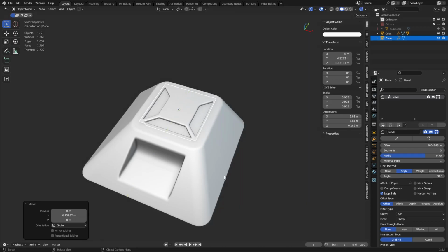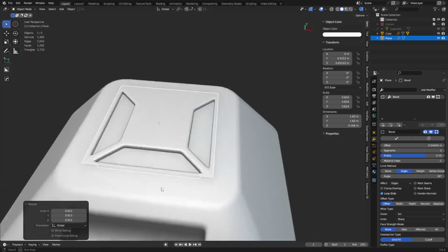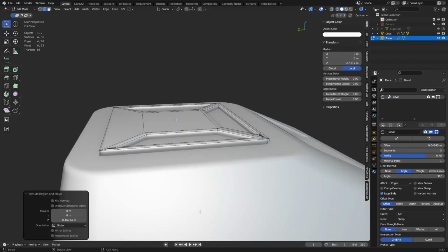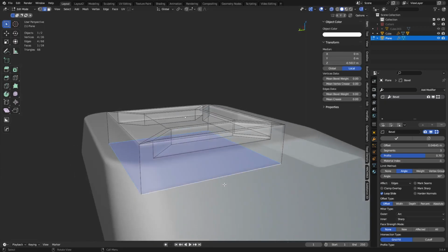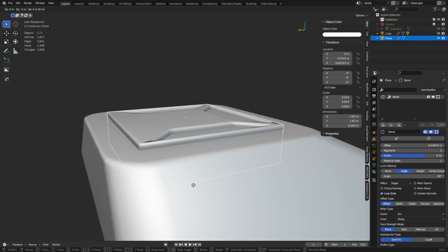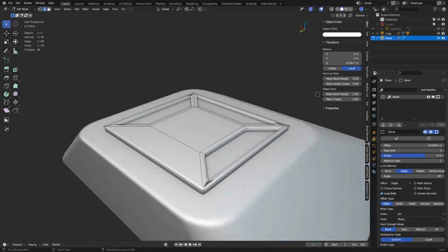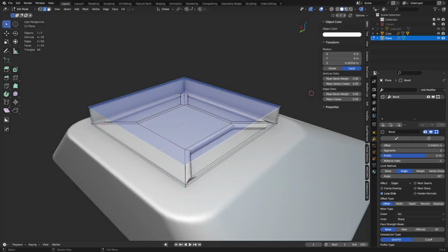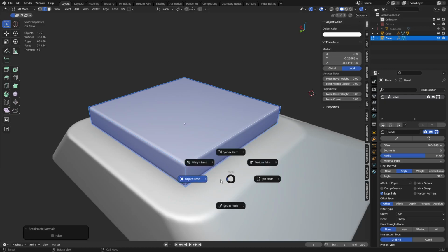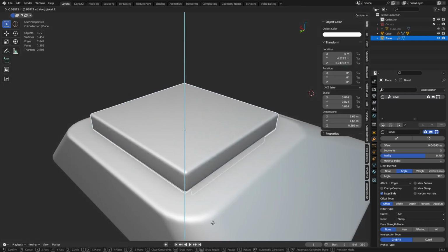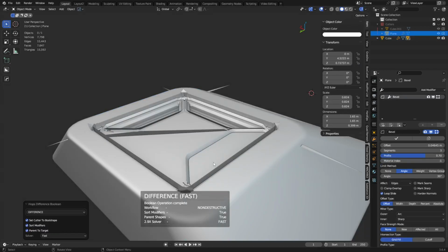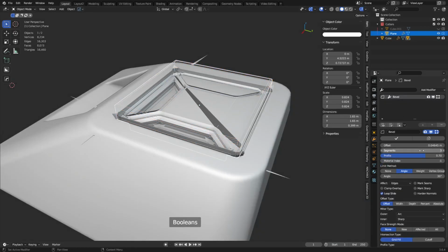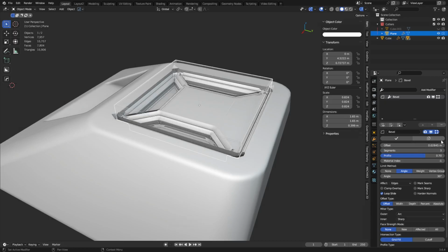Okay, so it's just a floater right now, but you could definitely finish out the shape doing something like an extrude all the way down, perhaps merging it. So we could do maybe a Boolean union, or let's see if we can do extruding up, pressing F, Alt N, recalculate outside. We should also be able to use this as a cutter, I think. And it might cut it right. It might go crazy. In this case, it went crazy. Because it might have a bevel on it that we don't need. We'll get rid of it.